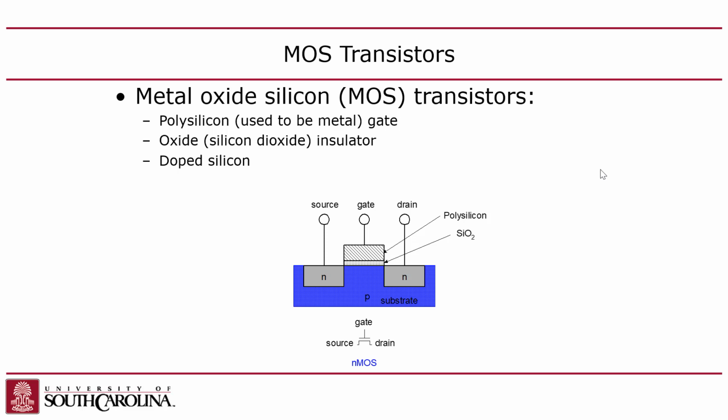So if you shrink that channel, then the charge carriers, which have a fixed mobility, you can't speed them up. I don't think there's any way you can speed up the charge carriers in a semiconductor, but you can give them a shorter distance to go. And so the shorter that distance is, the faster that thing will turn on, right? So you got to charge it, and then you got to get the guys going across the channel, right? So you want to make this channel as small as possible. And that's what that technology node is. When Intel says, we have a 7 nanometer process, that's what they're referring to, the channel length, 7 nanometers.